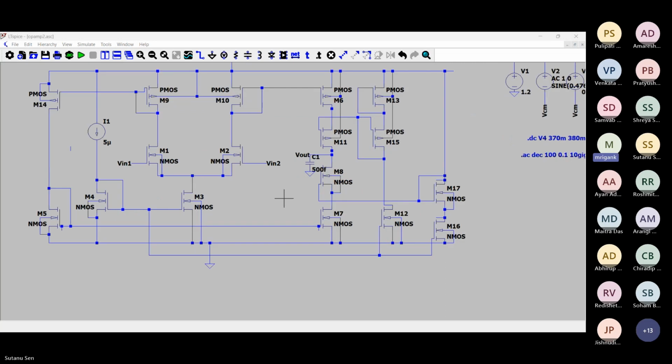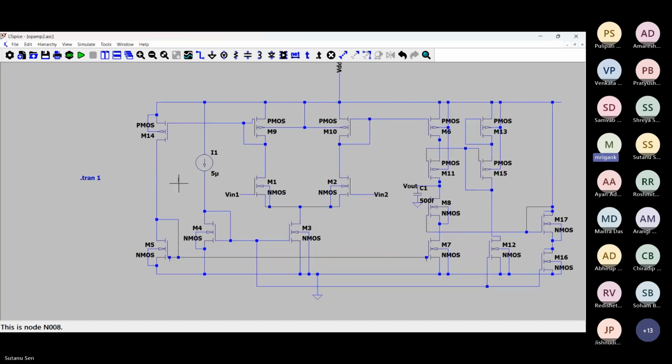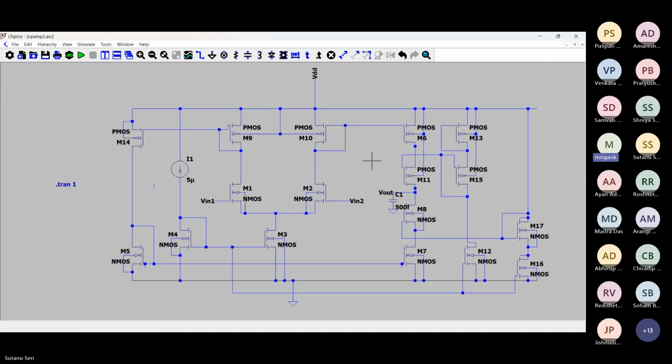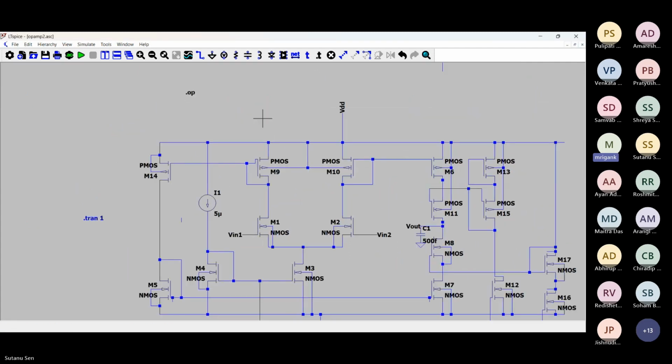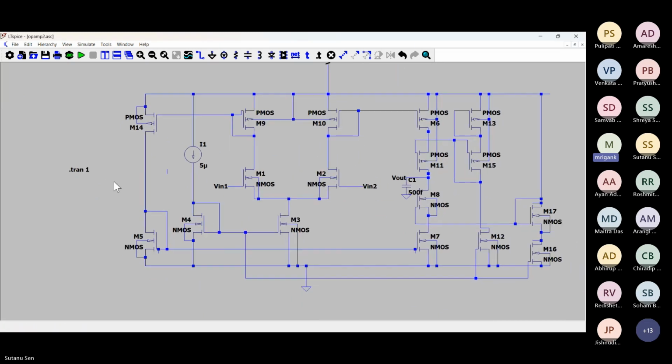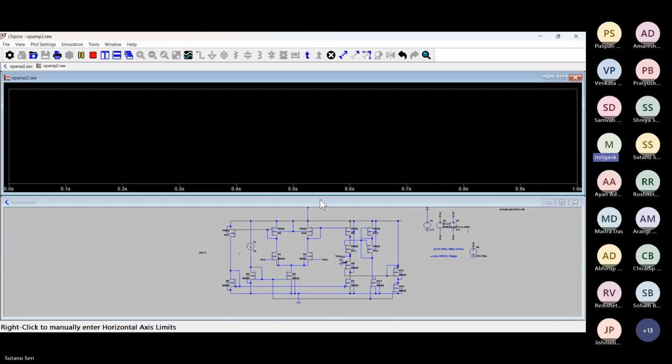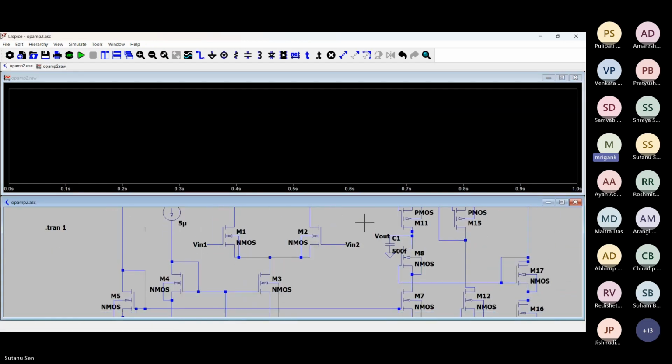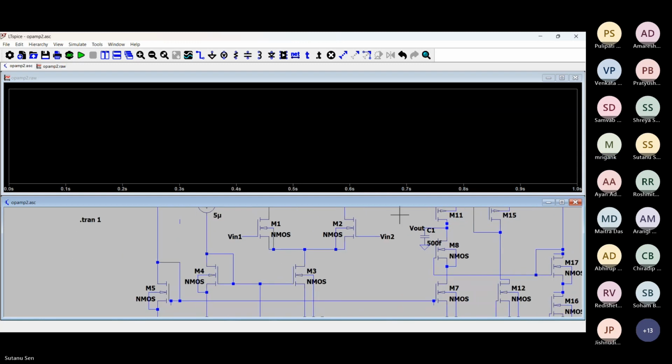What is the small signal current being produced? You can look at the drain current of M1 and M14, and likewise M2 and M6. How much small signal current is traveling from M1 to M14 and M2 to M6? Are they similar or very different?